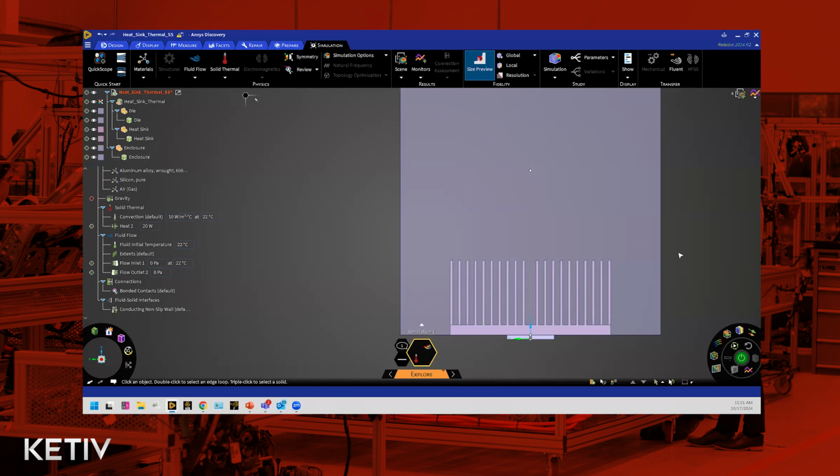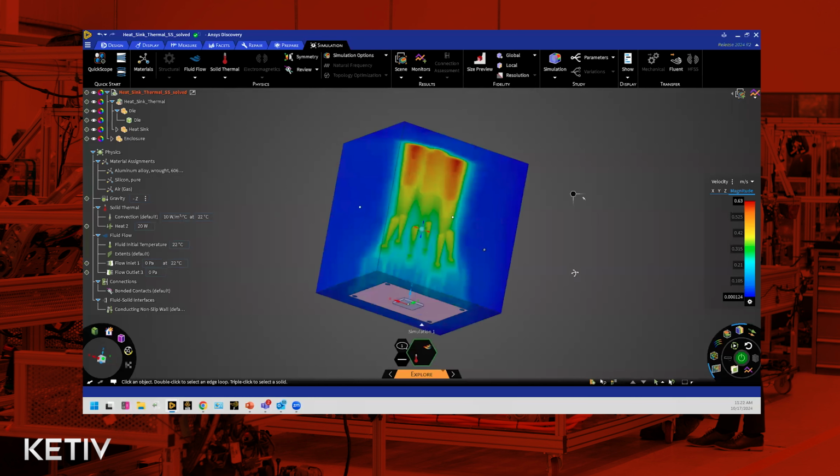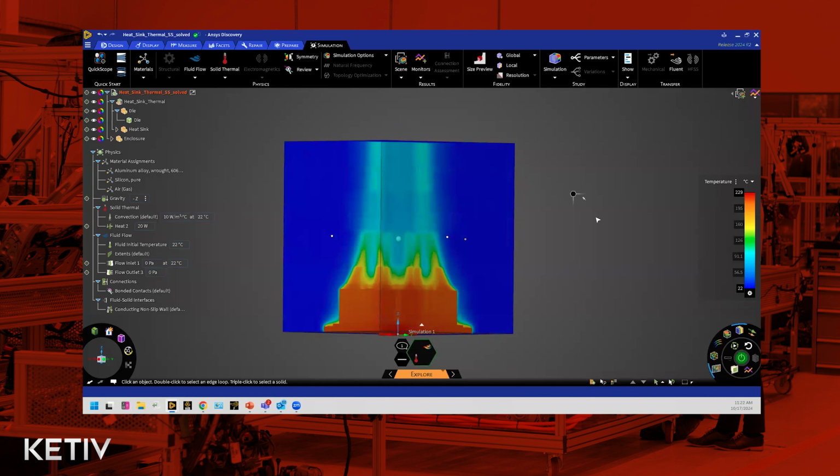There's nothing else to change or assign, and we can directly go ahead and click on the solve button. It takes a little bit of time on my machine, maybe 5 minutes or so for the solution to converge. So instead of making you wait, I already have the solved solution over here. You can see all the boundary conditions are similar to the first session that I was showing you, but this solution is converged. And what you'll notice here, let me change this to temperature, is the plume that we so often see with such natural convection cases.